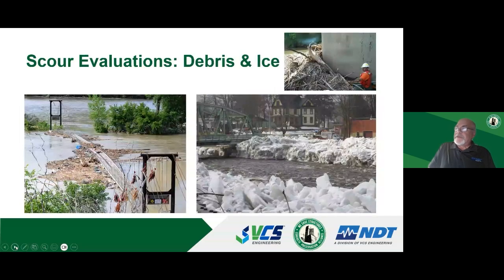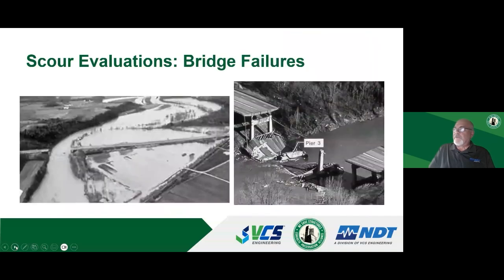And then, as Natalia mentioned, debris also contributes things. Tires, trees, what have you. In the Northeast in winter, during some of the springtime ice breakups, ice forces can be very dramatic and also impact the flow area. The water's not going to stop. It's just going to speed up. And if there's an ice jam, it may disturb that ice and dislodge it until it floats downstream and impacts against another bridge. Again, bridge scour is the number one cause of bridge failures all over the world.